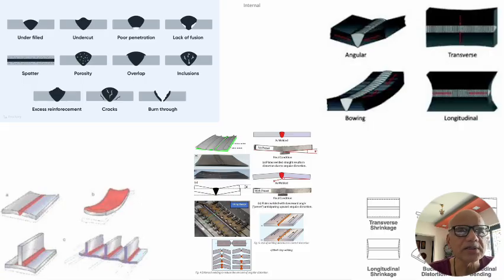The second defect is undercut, which is also a surface defect, and only an experienced welder will find it while he is welding, through his screen, but otherwise a new welder may miss it, especially the small fine undercuts which emerge on cooling.